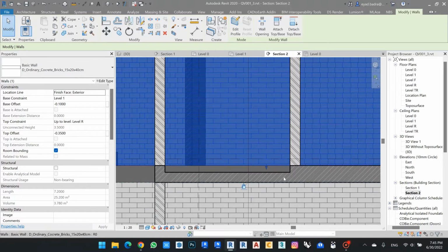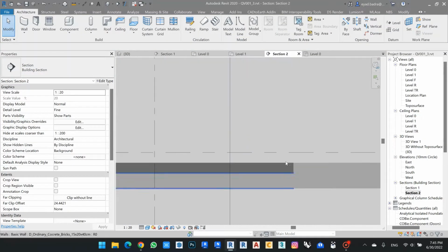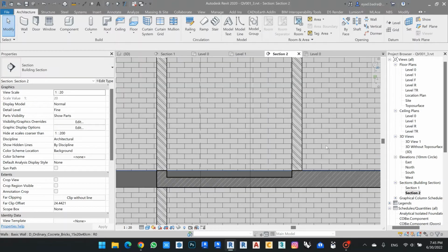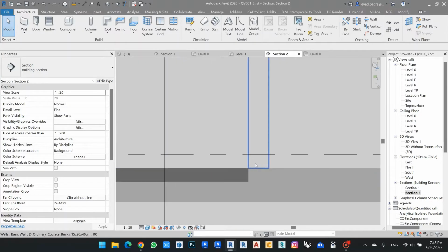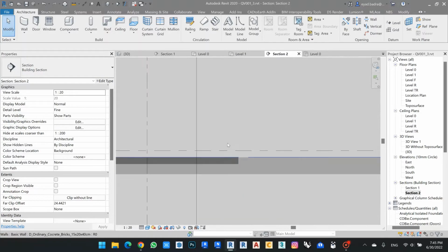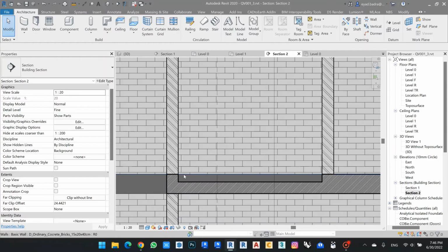The level of the bathroom is already in the slab 10 centimeters lower because of all the plumbing and MEP work. And this is my level of the finishing. It will be here, so approximately 20 centimeters between the slab of the bathroom and the level of the finishing. So let's start first to make the layers of my toilet.